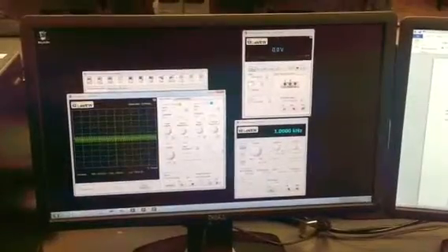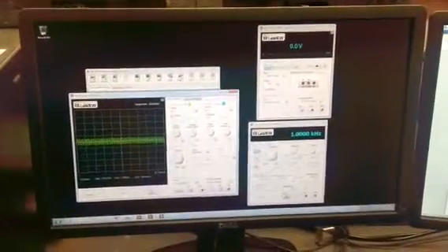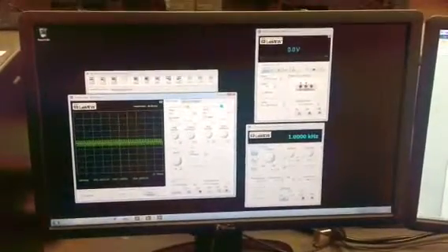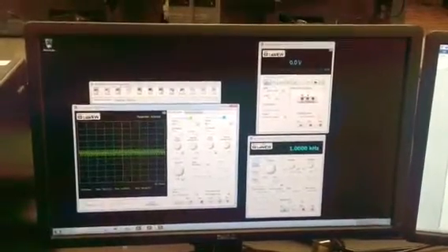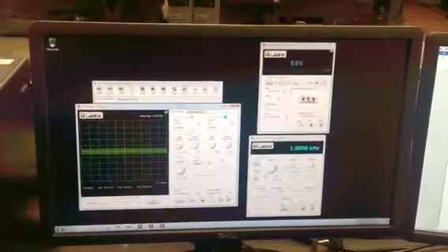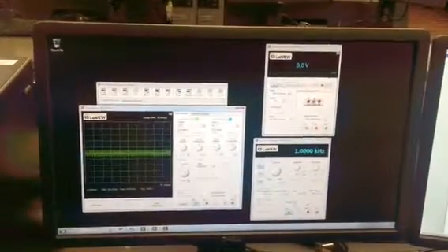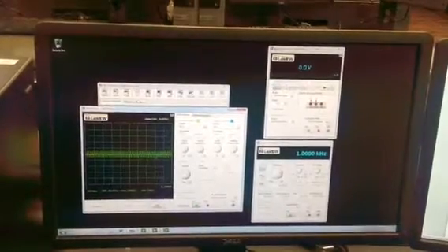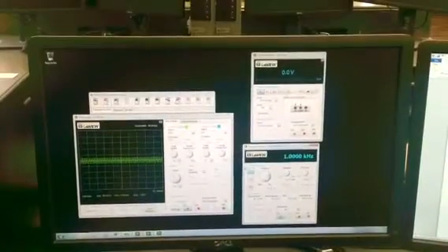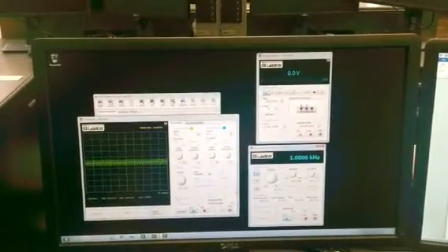Here we're going to set up our NI-Elvis function generator, and we're going to start by creating a 1000 hertz frequency with a sine function. Once we hit run, we can see our sine function on our oscilloscope. And the myDAQ and its corresponding software is now correctly configured to read various generated functions.